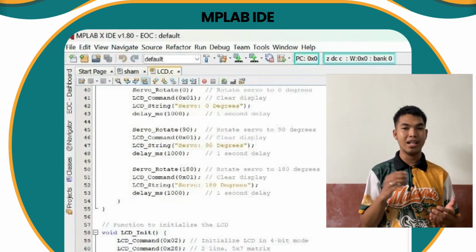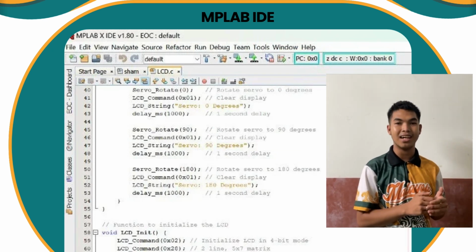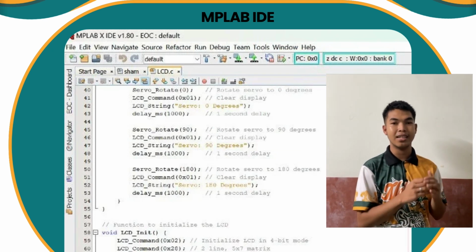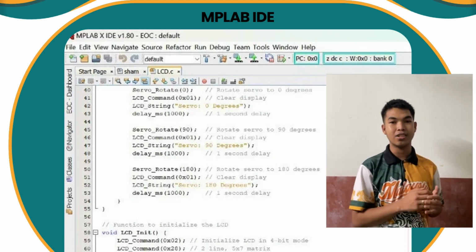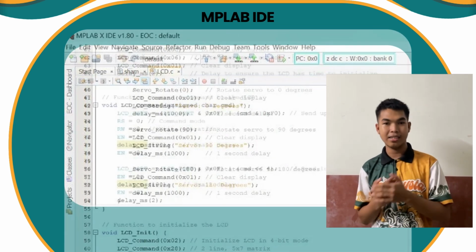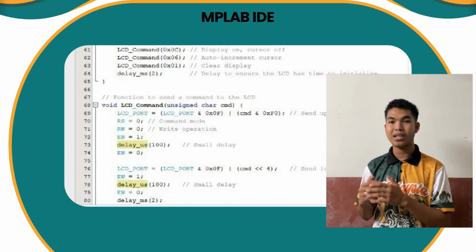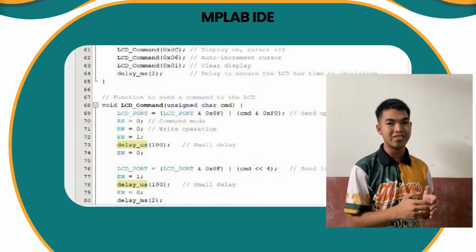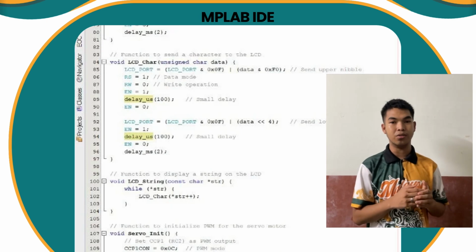For the LCD functions, we have LCD init, LCD command and LCD char. For LCD init, we set up the LCD in 4-bit mode. For LCD command, we send commands like clearing the screen and others. The last one is LCD char to display a single character, and LCD string displays a full string.